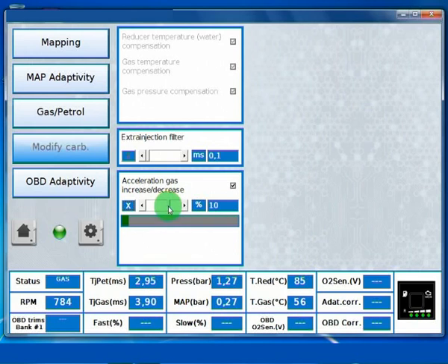Or maybe you can have a decrease of gas, mainly in CNG systems, because CNG in acceleration could bring a richer mixture and the car loses power. So to have a leaner mixture and a little bit more power while accelerating, you can decrease here, I think about 10%. However, you have to see on the car itself, and you will have better performance.